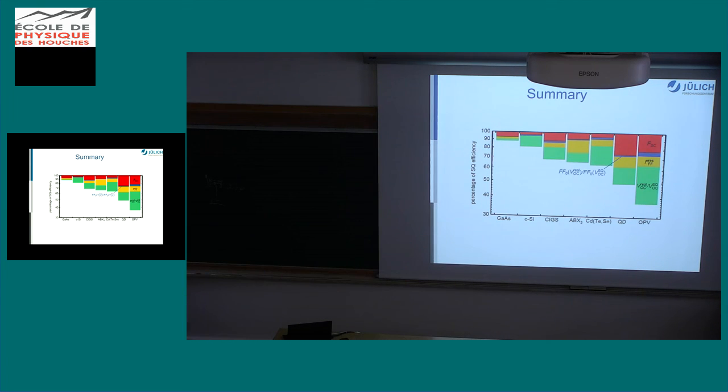Light trapping is very, very important, and they're doing really, really well with the silicon. There are not a lot of things, but that green one is very high, and that's the special point for the silicon, that you have this Auger recombination in there. The VOCs of the best heterojunction solar cells are already at the Auger limit. So for the VOC there is not much to do, but it's still non-radiative recombination. That's why it's so big if you compare it to the Shockley-Queisser limit. So silicon people next week can relax.